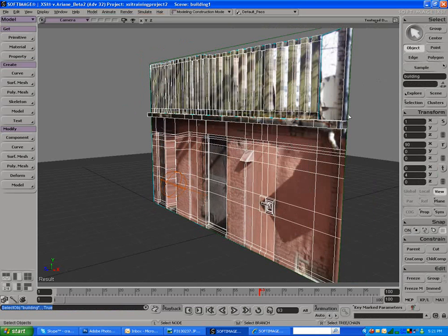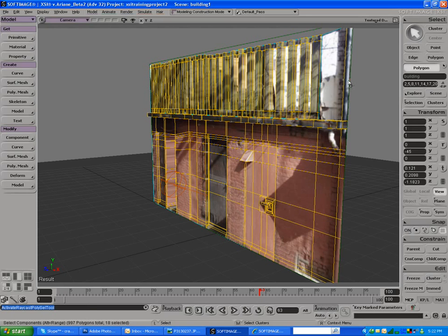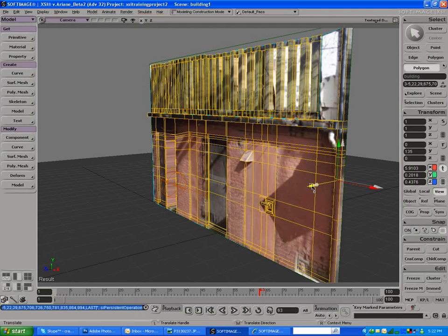We can fix that very easily if we need to, without deleting this extrude we just did. Say, well, I want that piece there and I need to add that pipe in. So we're actually going to go in and pick all those again. We'll just go to U, pick a face here, just go down the bottom. We can also do middle mouse and pick the whole strip, and just again hit Control D and move the whole thing out. But now we get that extra